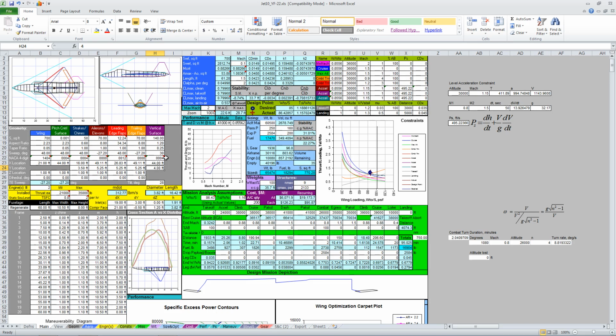Now they're hanging just a little bit off, but I can reduce a little bit more, so let's say 130. And there we go. The tails fit on the airplane. CN beta's good. We saved another 700 pounds. So 59.8. Oops, too many zeros. 59.6. Alright.